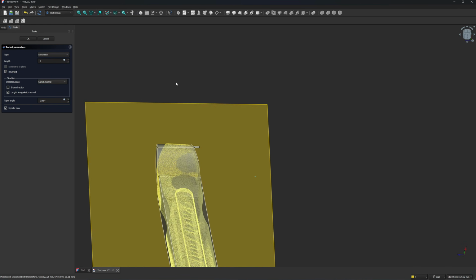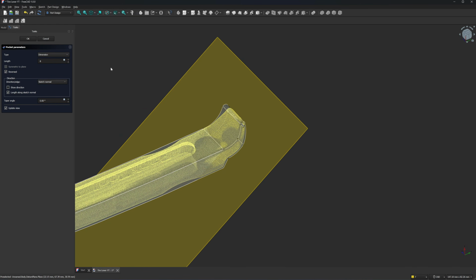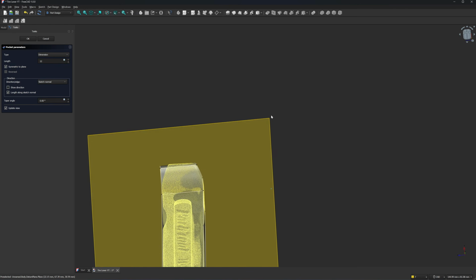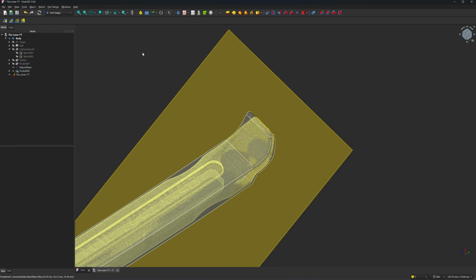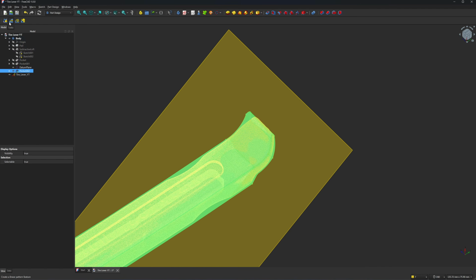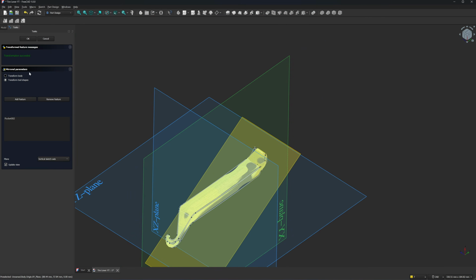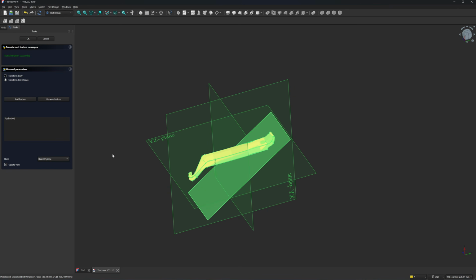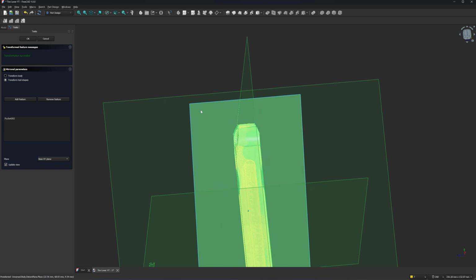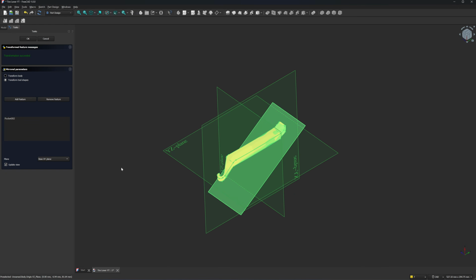Okay, now I cut one side. Now let's try symmetric, 12. Right, so I cut symmetric, 12 millimeter. Click on OK. Next, I'm going to, can I mirror it? Polar. Okay, mirror. I can mirror the feature and to this plane. Transform body. Base X, base X, Y. Okay, I can mirror the feature by using XY plane.